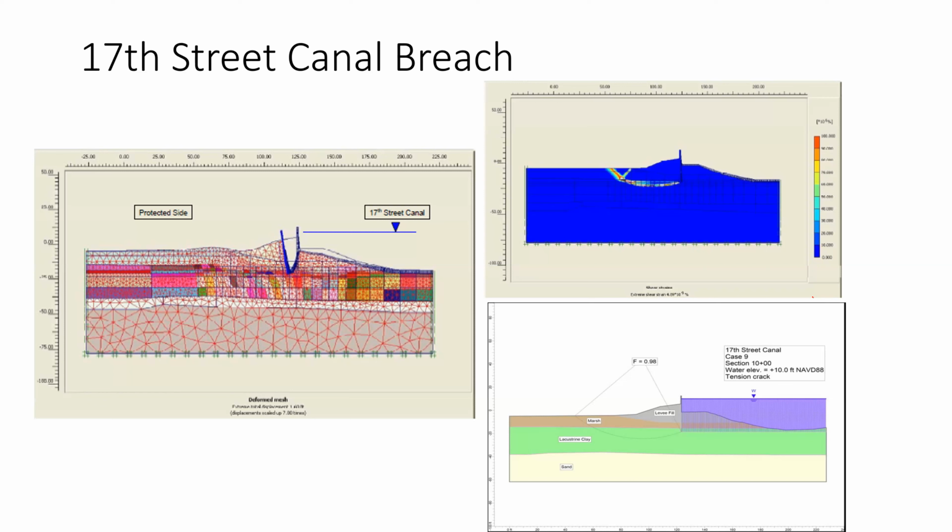Now look at this. It's supposed to have water on top, right? The water table is somewhere here, but it moved. So now the height goes down, right? When the height goes down, now the water can overtop, right? So the T-wall, I think it's the T-wall right here, moved and water goes on top of it. Basically, it's a problem with your backfill on the backside and the foundation failure.